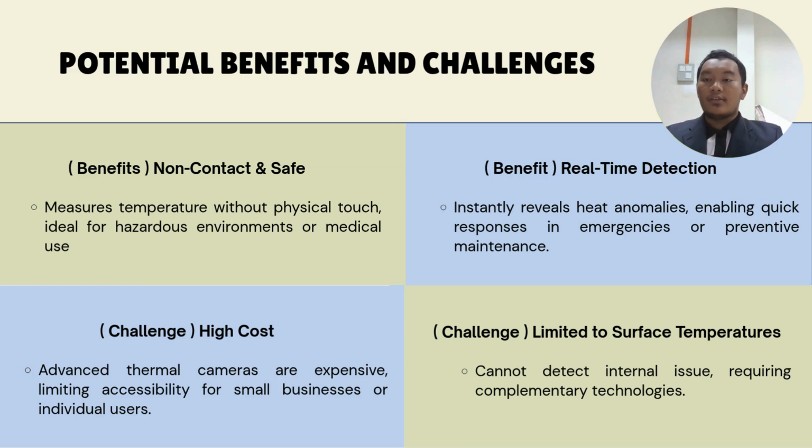The first challenge is high cost. Top-tier thermal cameras are investment grade. It is hard for small teams. But hey, the prices are dropping as technology evolves. The last challenge is that it is limited to surface temperature. It cannot detect internal issues. It requires ultrasound or X-ray for the full picture.